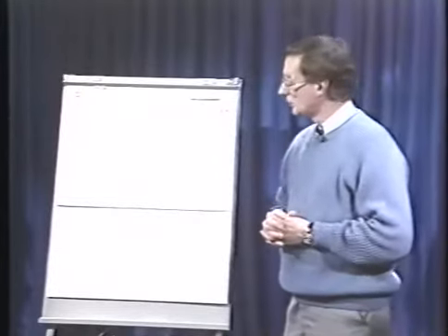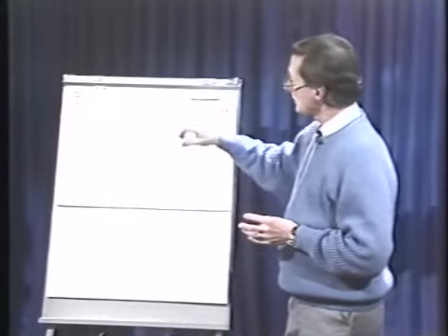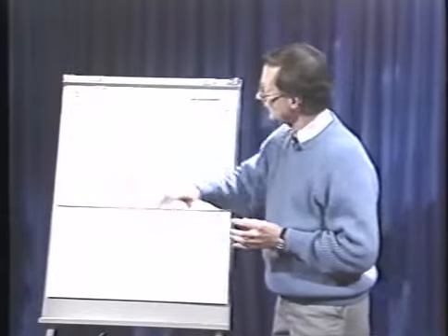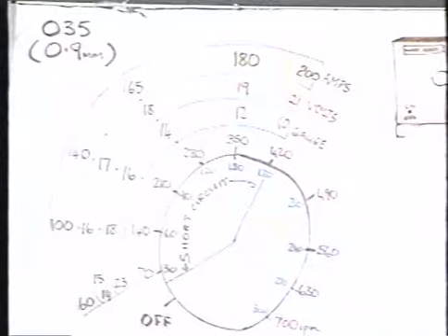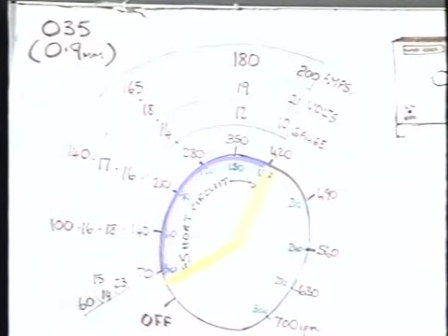First of all, if we look at a wire feed control simply as we would look at a clock, from the 12 o'clock position, the 1 o'clock position, we can see that the short circuit range traditionally goes between the 7 o'clock position and the 1 o'clock position on a normal wire feeder, which means it's running around 50 IPM to about 420 IPM.